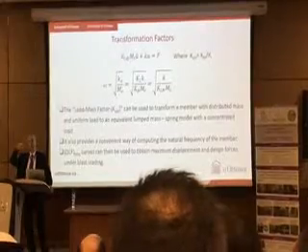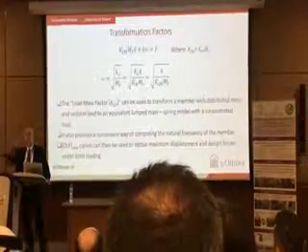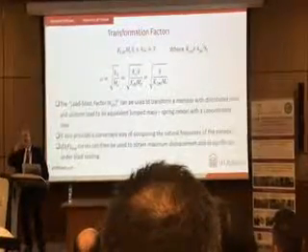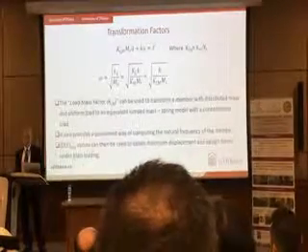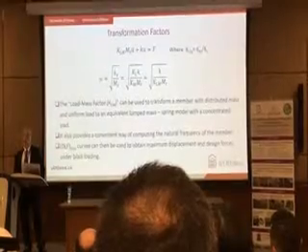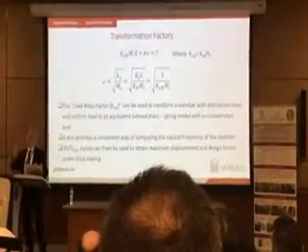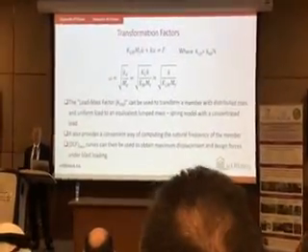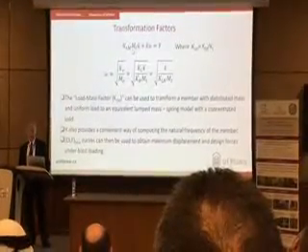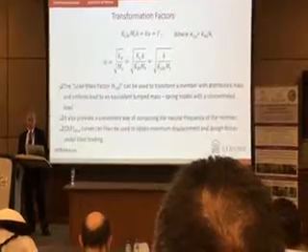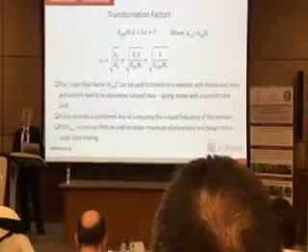If you have a triangular distribution of load or uniform distributed load, it generates different deflected shape. And stiffness is related to deflected shape, hence they are the same. So if I divide all terms with transformation factor for load, these two cancel, and I have now load mass factor.